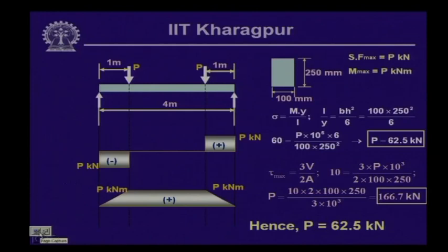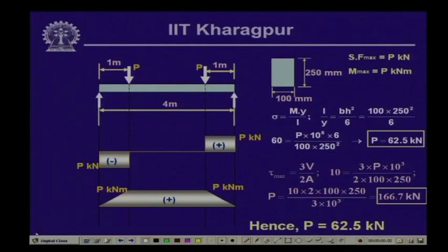So, if we compute the bending moment and shear force diagrams, as we have seen, the first step is to evaluate the unknown reactive forces. Let us call the beam ends A and B, and end A is on a hinge. So, you have a vertical force R_A and a horizontal force H_A, and a vertical force at B as R_B; they are the reactive forces. Now, summation of horizontal forces equal to 0 will give you H_A equal to 0. Now, we can compute the values of R_A and R_B.